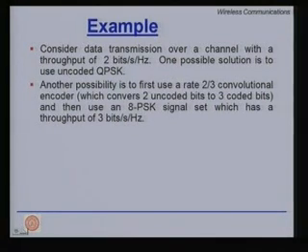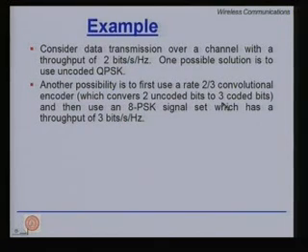So, what did we do? In the constellation diagram, if we are not going to expend more power, we have brought the constellation points closer together. So, by going from QPSK to 8 PSK, we have actually increased the probability of error. We know that. However, before doing that, we have already added some redundancy by using a convolutional encoder. Now, convolutional encoder will try to do error correction, thereby reducing the probability of error. Moving from QPSK to 8 PSK has brought the constellation points closer, thereby increasing the probability of error.